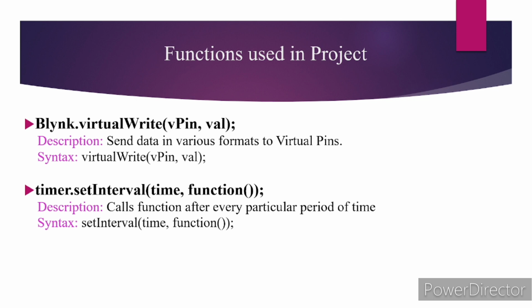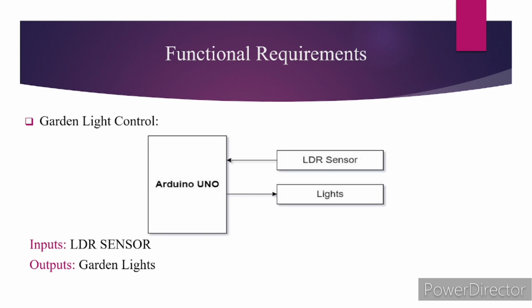Next is Blynk.virtualWrite. This function sends data in various formats to virtual pins. And the last is timer.setInterval. This function calls the functions after every particular period of time.